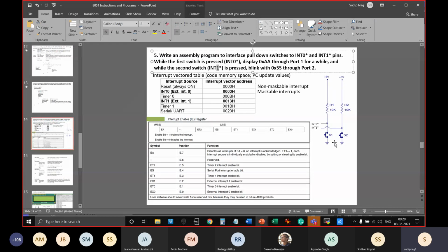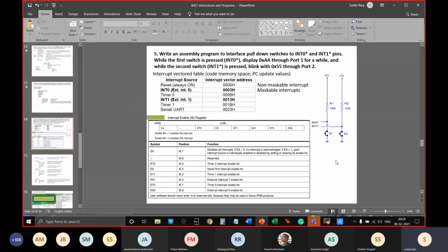Now, at this point, I would like to make a disclaimer. Some of you must have studied ARM and AVR at your leisure or as a hobby for other projects. You will find one difference here with the 8051 and those AVR, MSP430, PIC or even ARM. The difference is that in 8051, we do not use a separate register for configuring the direction and purpose of an 8051 pin. I'll repeat it.